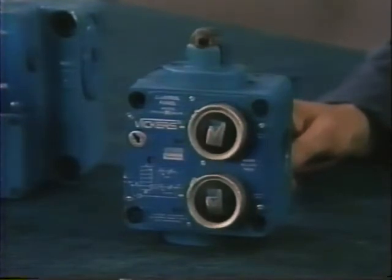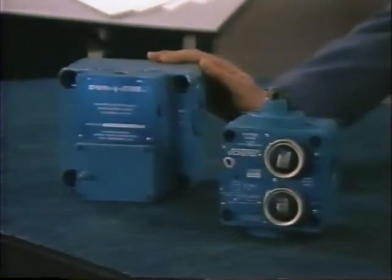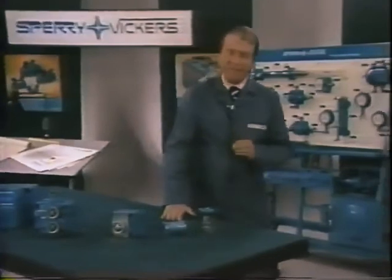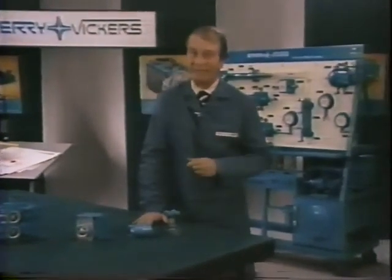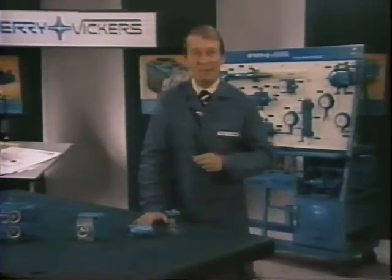No oil lines are connected directly to the valve body. And finally, we have a large valve which can be electrically modulated to allow us to control flows up to 60 gallons per minute. Okay, that concludes our discussion of flow controls. As you've learned, the speed of an actuator depends on how much oil is pumped into it, and flow controls regulate that speed. This has been Chapter 6 in our 8-part training series on the basics of hydraulics.